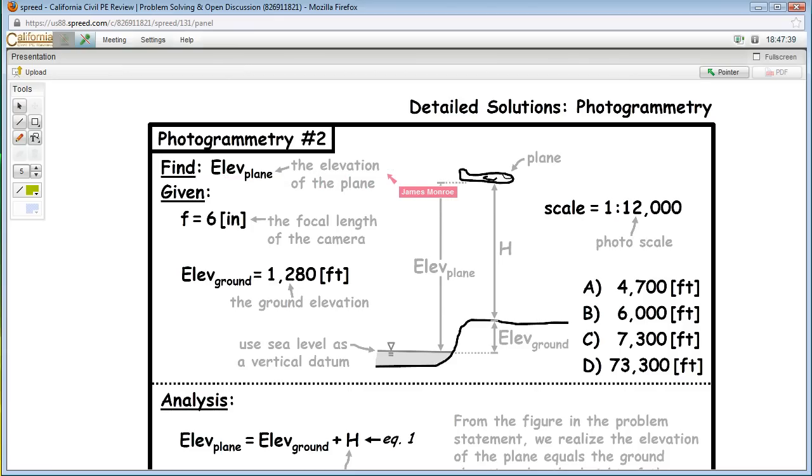That's another way of saying flight height is the typical terminology that's used. Flight height is always taken from the ground up. A lot of people think it's going to come from something like mean sea level. It's not. It's always from mean terrain, it's called. So that's one major bugaboo people have. So when we talk about the flight height, we're talking about h.